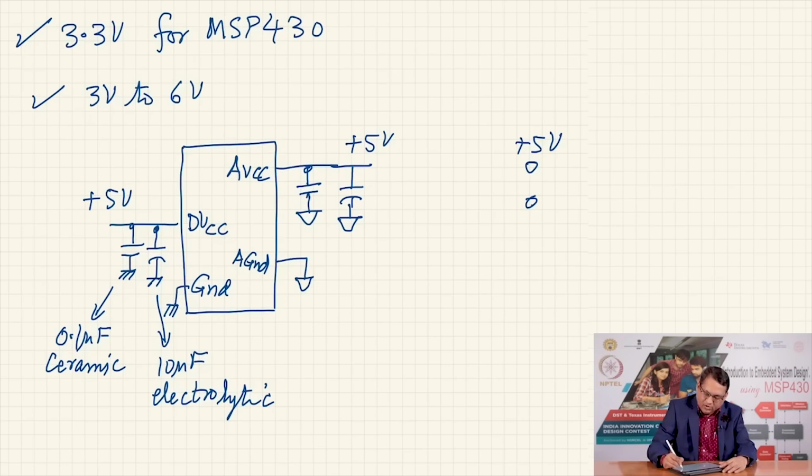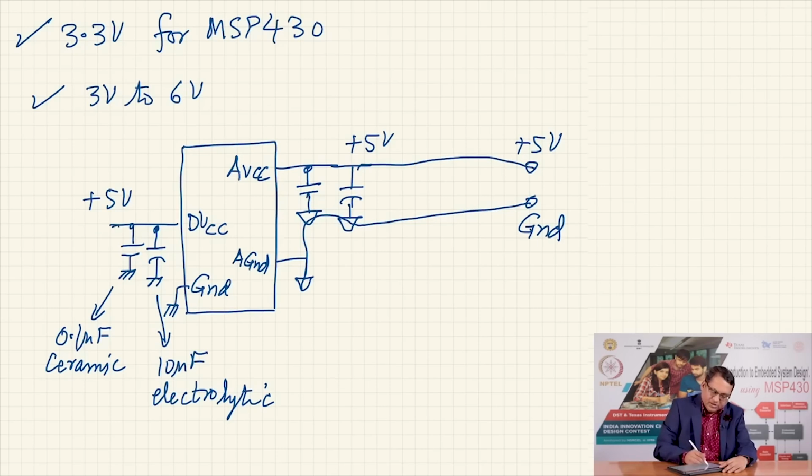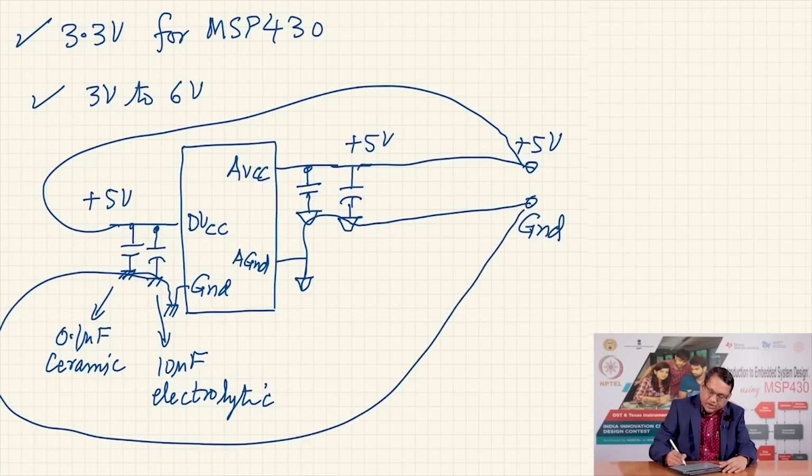The way to ensure that these analog grounds are not directly connected to the digital grounds on the microcontroller pin is to route them separately using separate tracks. Similarly, you have separate tracks to go here, these are all connected together and then they go here. If you keep the tracks separate, it would serve the purpose of isolating the noise which is often generated on the power supply pins because of the internal switching action in the logic circuit, and it will not corrupt this power supply voltage.